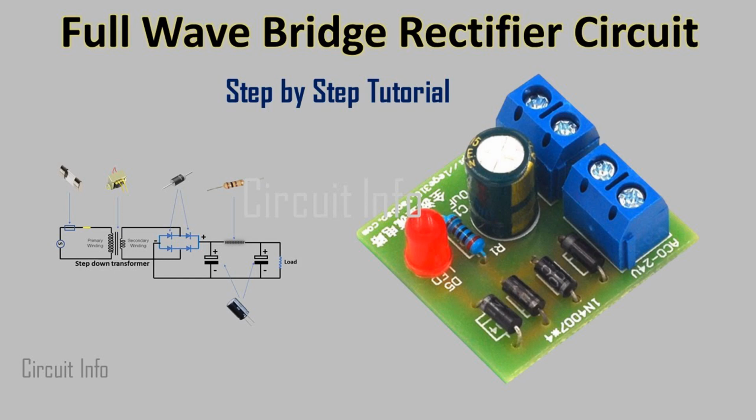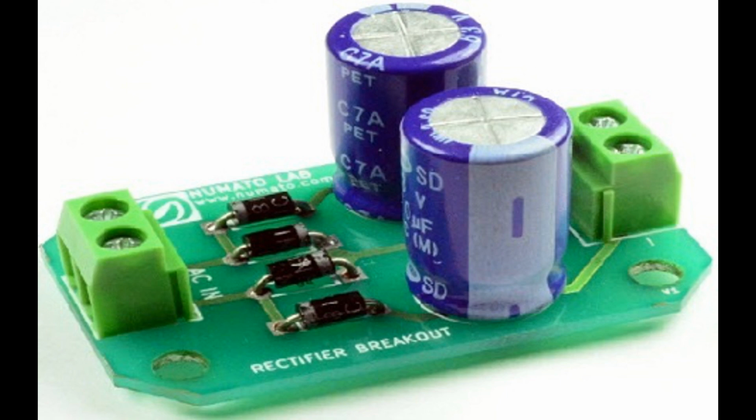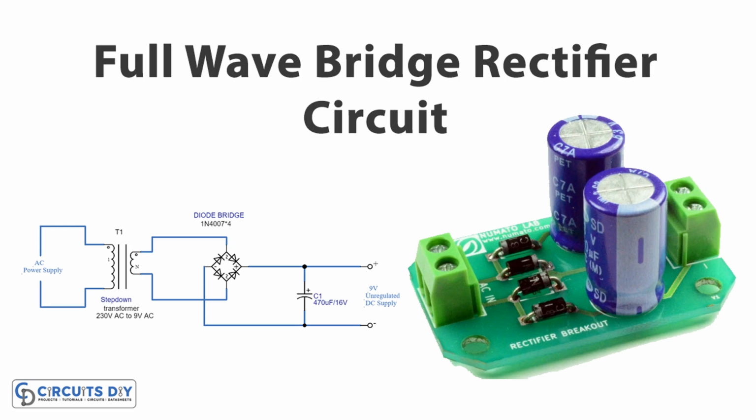Integration with power distribution systems. Battery backup systems are often integrated into larger power distribution systems, such as data center power distribution units, PDUs, or building electrical systems. Bridge rectifiers ensure compatibility between the AC power supply and the DC power required for battery charging and inverter operation within these systems. Overall, bridge rectifiers play a crucial role in battery backup systems by facilitating the conversion of AC power to DC power for charging backup batteries and ensuring reliable operation of critical loads during power outages or disruptions.